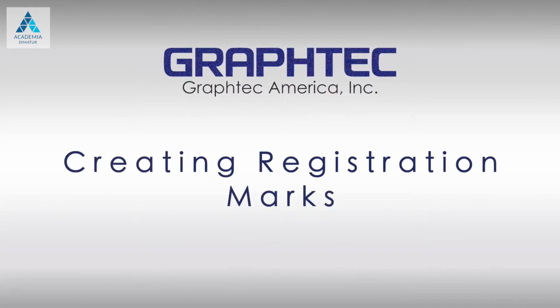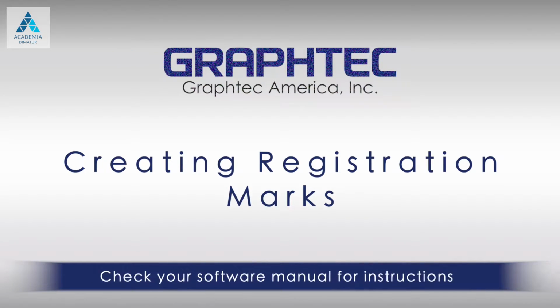In this part of the print and cut segment, we will cover how to create registration marks using Cutting Master 4. While we will be using Adobe Illustrator with the Cutting Master 4 plugin, the steps are generally the same with Corel Draw and with Graphtec Studio applications. If you use a different application, the steps are likely the same, but it is best to check your software manual.